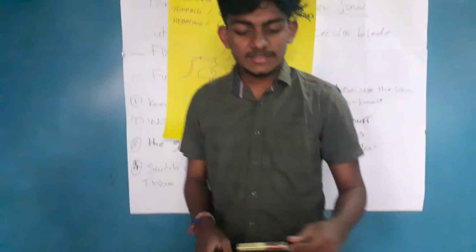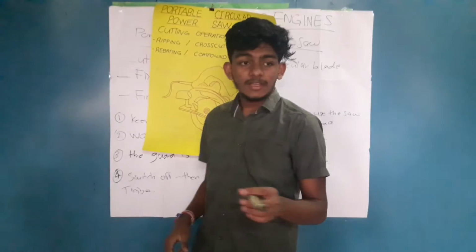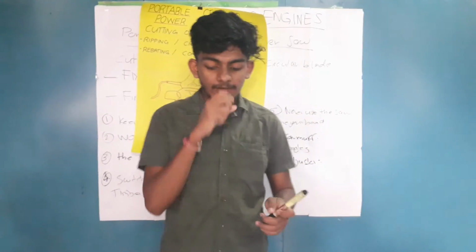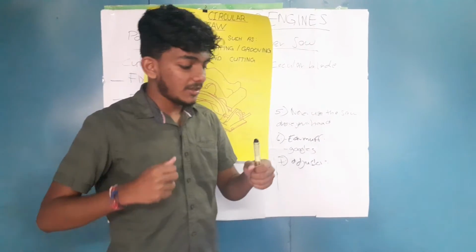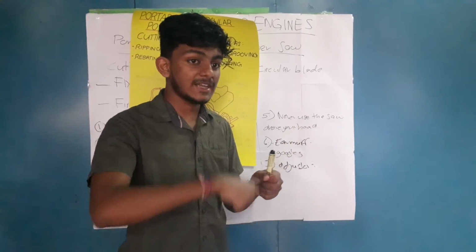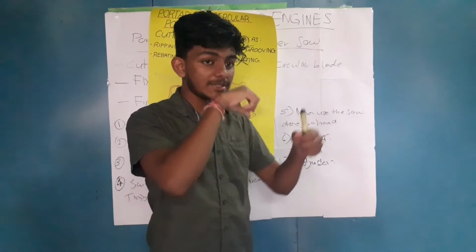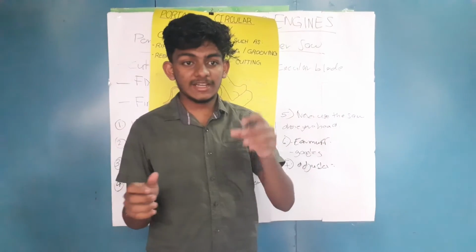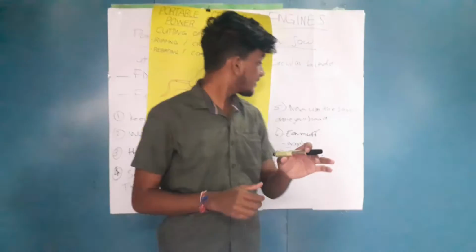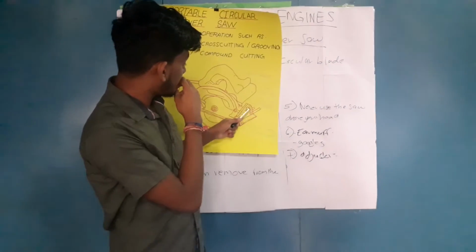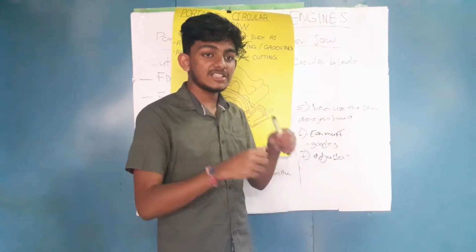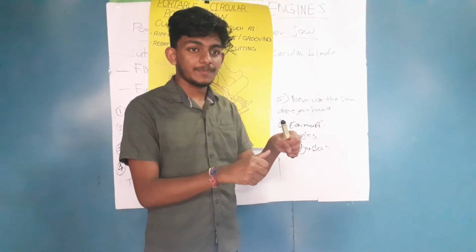Alright, class, since the video presentation is over, have you seen how the blade guard goes up while you are cutting? Right, that's how a blade guard works. It automatically goes up once you are cutting, and it automatically comes back down. Sometimes it gets stuck, so you have to pull it down. You have seen how an adjuster was controlled? Right, the adjuster was here, the protractor scale, and how it is done, and how easy it is to operate a circular saw.